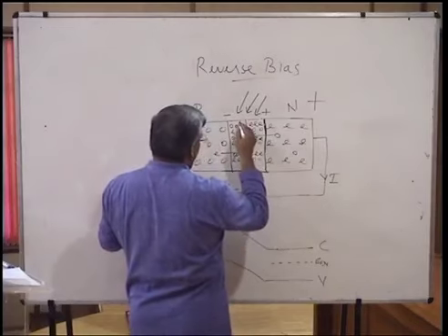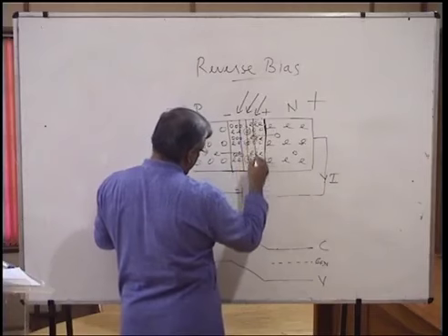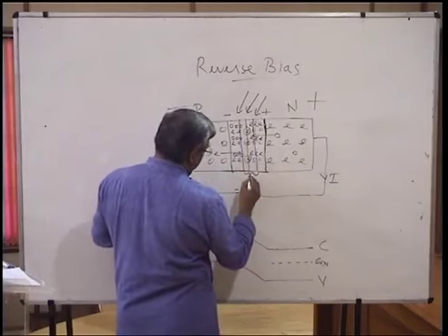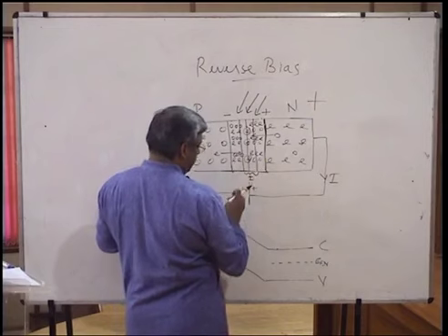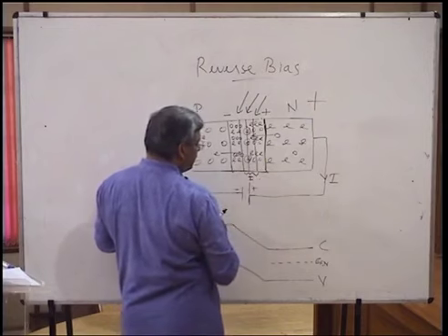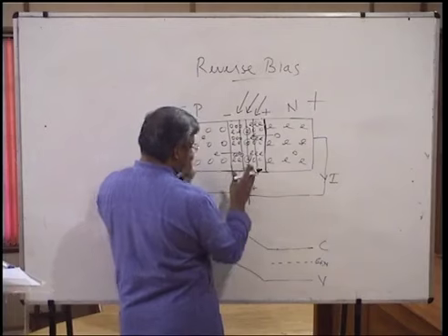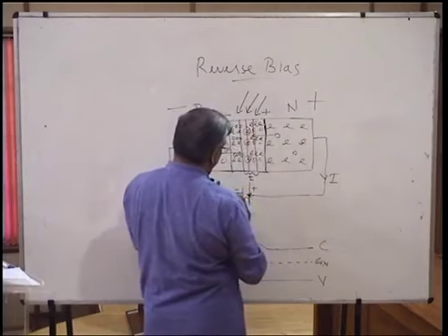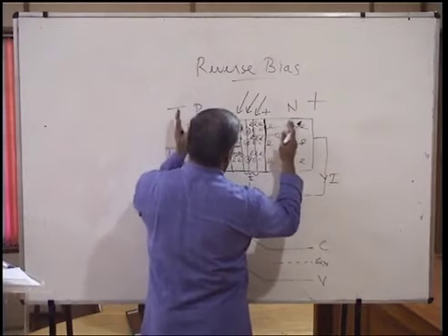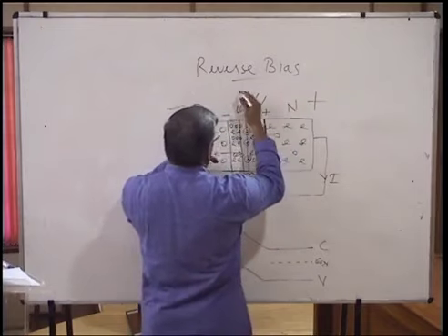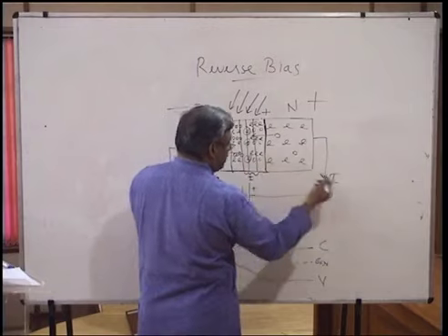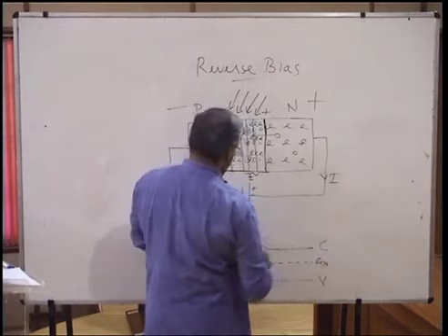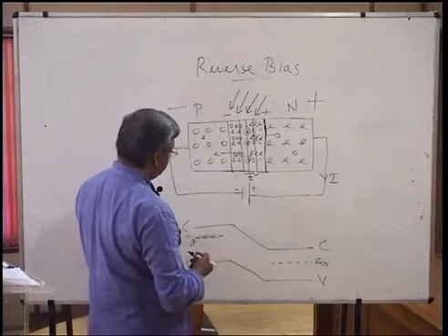Therefore, you can think about adding a region using an intrinsic material, which I already explained in the first part of this lecture. Intrinsic material is sandwiched in the middle of the depletion layer, so that you are expanding this particular depletion layer where you expect the light to fall, whose intensity has to be detected or measured.